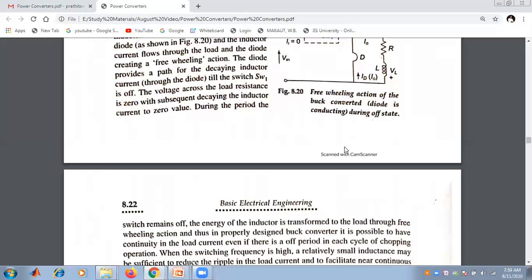The ripple comes from the incomplete suppression of the alternating waveform after rectification. So we can say that the ripple is nothing but wasted power and has many undesirable effects in a DC circuit. It heats the components, causes noise and distortion, and may cause digital circuits to operate improperly.